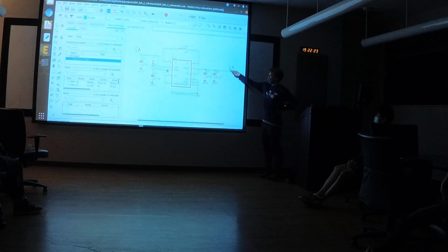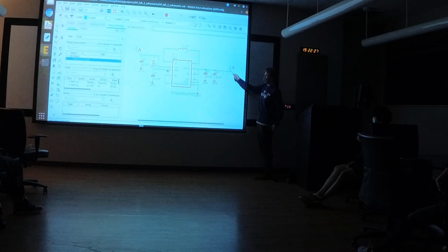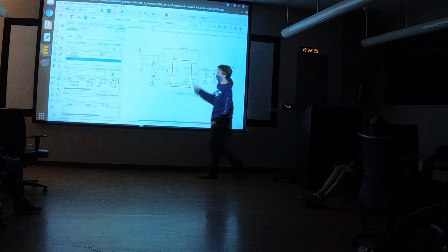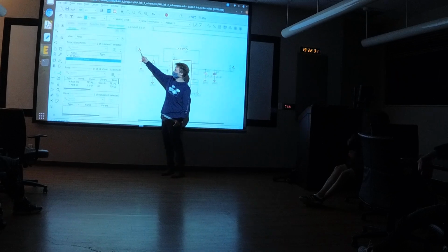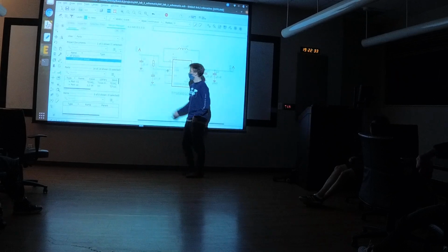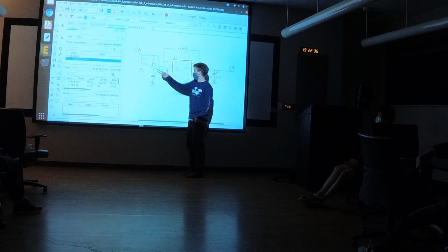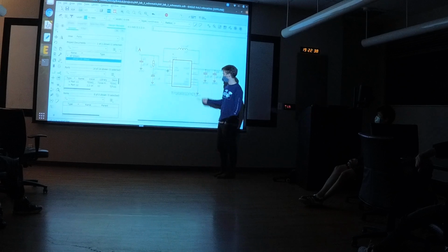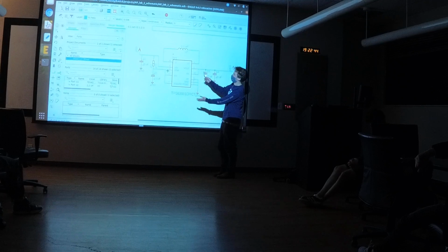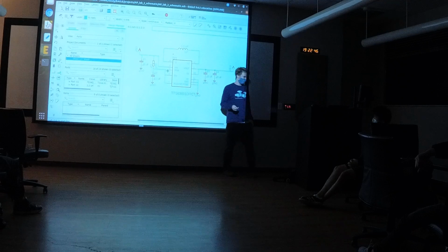We added the labels here, so anything that's connected to another 3V3 arrow will be connected to this, which is what we want. If we connect the battery to VDD, these two will be connected. We have a resistor, we have all the capacitors that they asked for. We connected these 3 pins to ground, which is important, because otherwise it won't work. It works, or it should work, in theory.